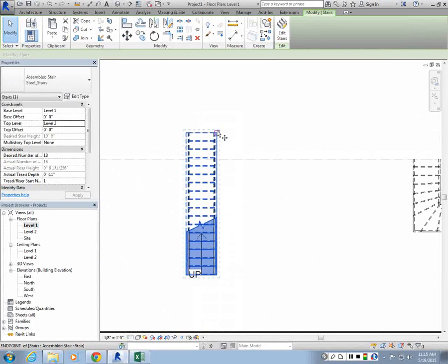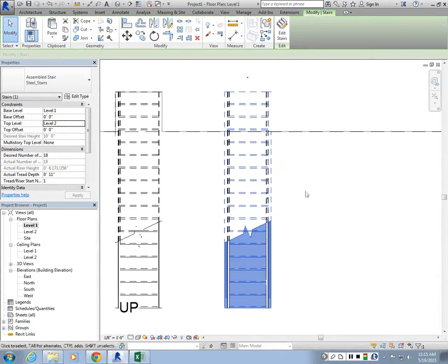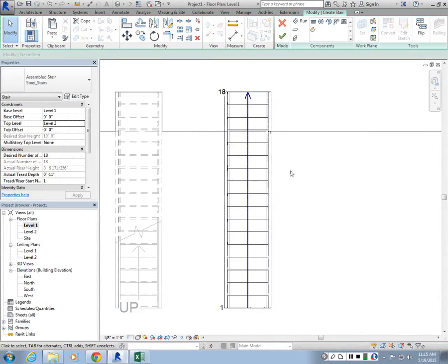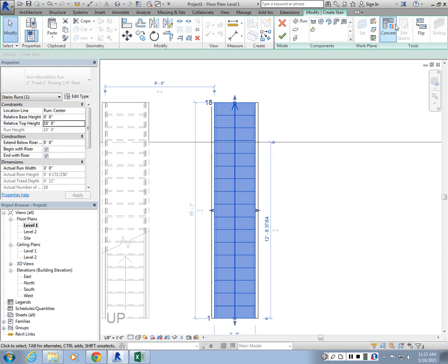One last thing I want to show about the stairs, you can also do them using sketches. So if you choose any stair you created, I would first recommend you to play around with it by starting with an actual staircase. You can choose it, go to edit stairs, choose the run, and under the modify ribbon here, there's convert to sketch based. So once you do this type of conversion, you'll be able to edit the individual lines of the risers and the treads. But this is an irreversible process, and Revit tells you that as well.